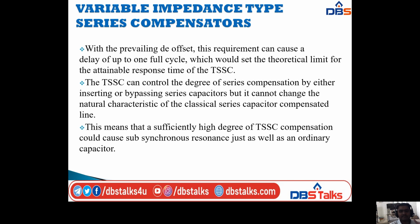With the freewheeling DC offset, this requirement can cause a delay of up to 1 full cycle, which would set the critical limit for the attainable response time of the TSSC. The TSSC can control the degree of series compensation by either inserting or bypassing the series capacitors, but it cannot change the natural characteristic of the classical series capacitor compensated line.